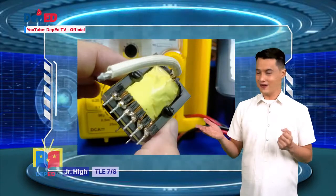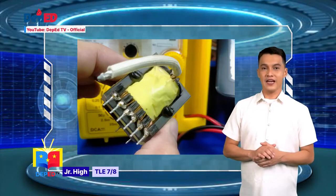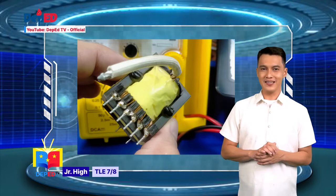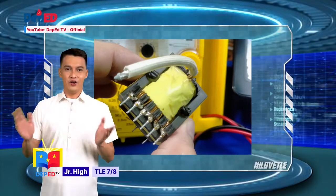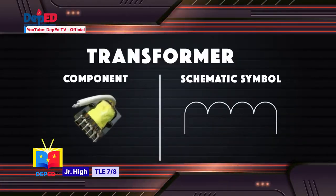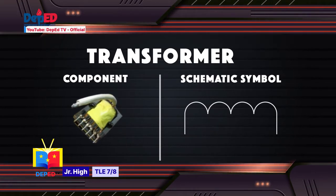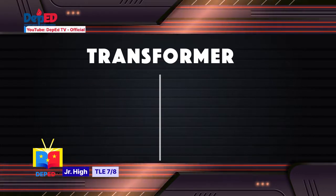A transformer is a device with primary and secondary windings. It will transfer power from the primary windings to the secondary windings through induction. An open primary winding will prevent any primary current, and therefore, there will be no induced voltage in the secondary winding, and no voltage will be present across the load.